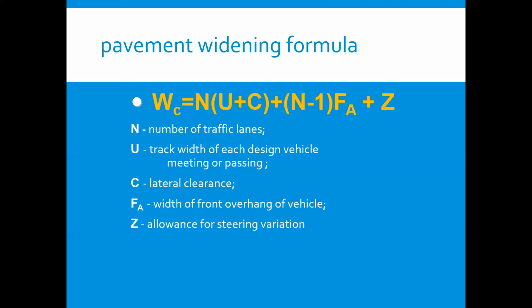The curve widening calculation results in very wide traffic lanes for curves with a radius less than about 100 meters. However, at traffic flows greater than about 1,000 vehicles per day, cars tend to form two lanes within traffic lanes greater than about 4.6 meters wide. Therefore, designers should be aware of potential problems that may occur in an urban area with wide traffic lanes due to curve widening.